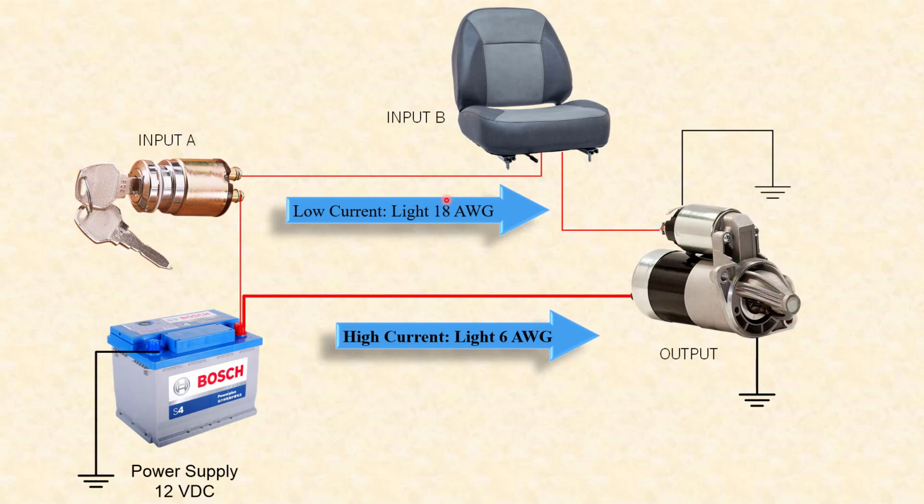And once I let off of the starter, that has a spring return and it flies back in, the contacts open up so that the starter doesn't keep trying to run after the engine started, but also it disengages that gear so that the flywheel doesn't try to run the starter off of that gear. So two functions: to close the contacts for this electrical circuit to drive the motor, and to engage and disengage the flywheel from the starter.